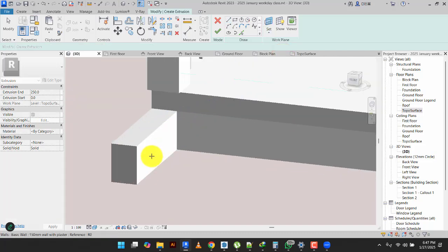Then you come here, then click here as a work plane. Then I can now go for my drawing tools. See them. Now choose line. Then I'll draw what I want. So I want to go up. Here's 300. I'll come up 300 there. My thread.